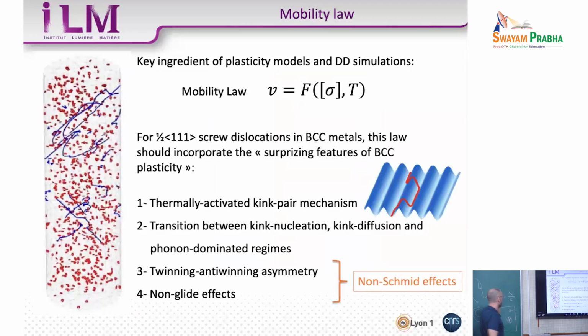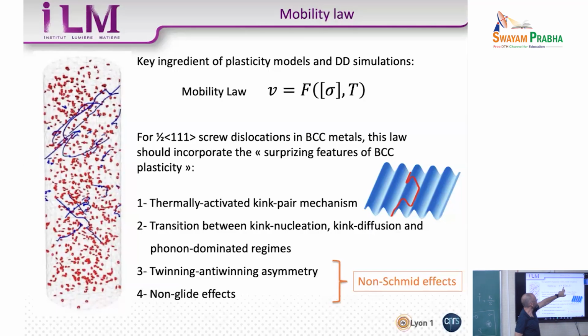So what is the mobility law? The mobility law would be this function here, which would be a function of, in principle, the applied stress tensor, the full tensor, and the temperature. And that function gives you the corresponding velocity for a dislocation segment, right?